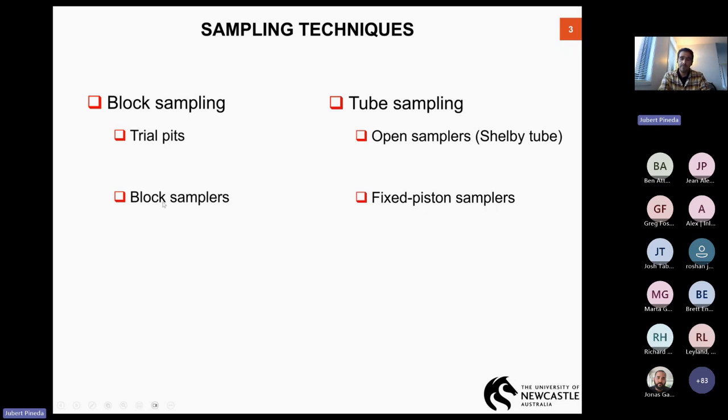Before moving forward, I'm going to give you my very first conclusion for this webinar. I will try my best to highlight the fact that Shelby tubes are not by any means a good option for sampling soft soils. I strongly do not recommend the use of Shelby tubes, and I know that sometimes this sounds a little bit too strong for practice, but I will try to give proper scientific justification for that statement.